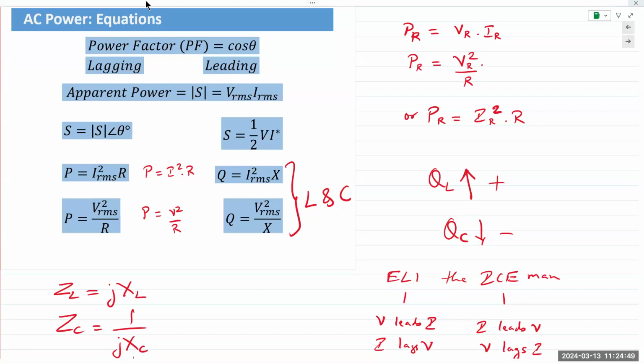We do actually measure it. We use the impedance bridge to measure the values of the inductor and the capacitor, and it also gives you the quality factor. It just performs a calculation inside the bridge or inside the meter.